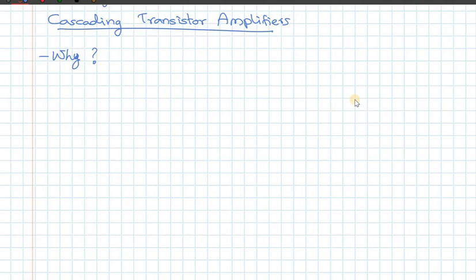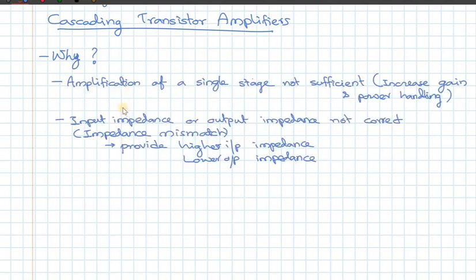For example, if you have input and output stages made up of common collector amplifiers, you can have high input impedance and low output impedance. But to achieve the high gain, you can then have a common emitter amplifier stage in the middle, maybe one, maybe more. This is what we are going to do in this section of the lecture. So let's look at how to achieve such an amplifier. All this input and output impedance matching is done to minimize the impact of loading.